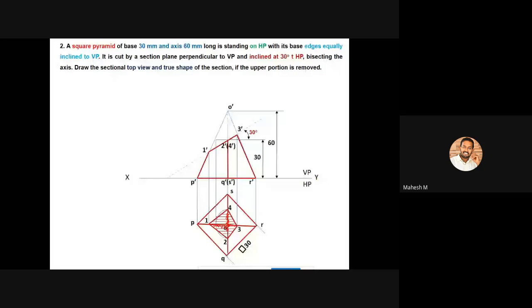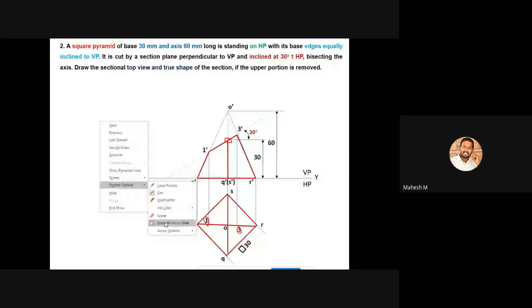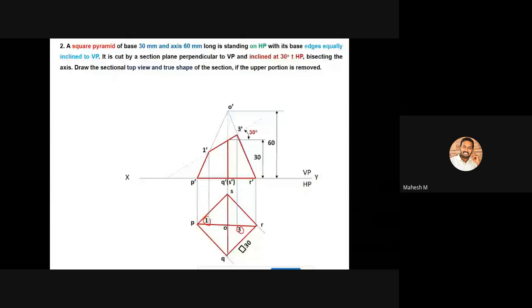Okay. So I'm going to say again how to draw this point 2 dash or 4 dash. Okay. So now you got, we have projected point number 1 and also 2, 3. So first of all, you have to project this axis cutting point towards any one slant edge, and at that point you'll be having one more, you have created one more corner.